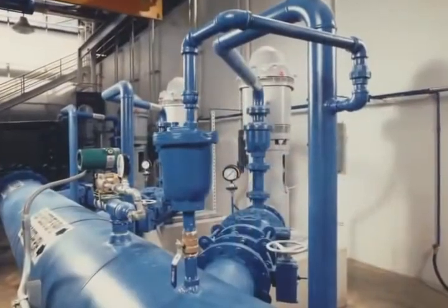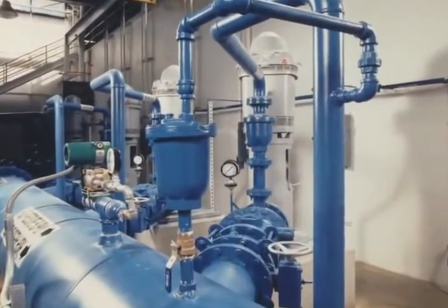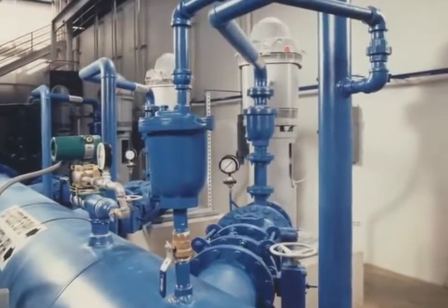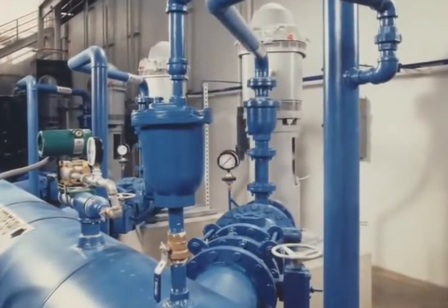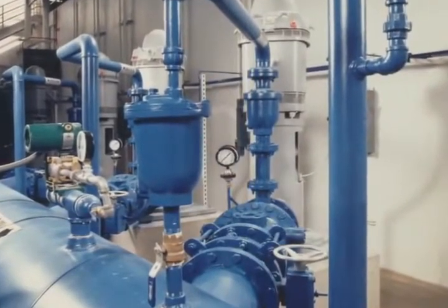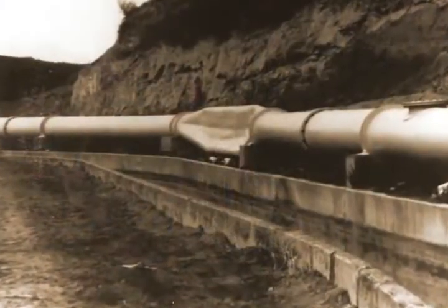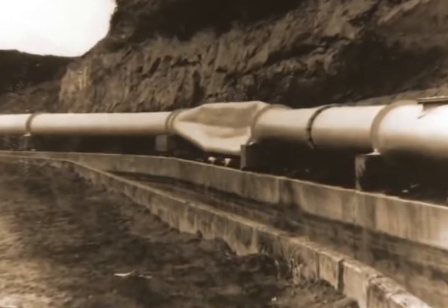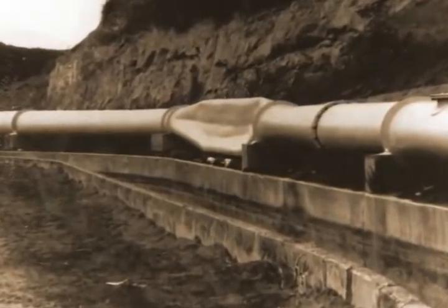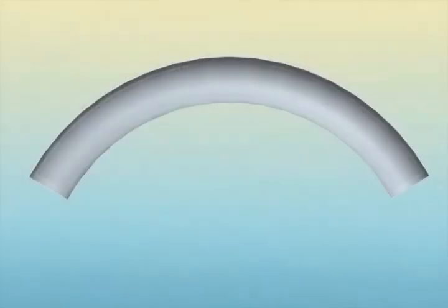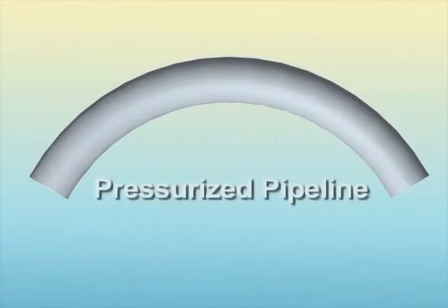In reality, many of these problems are not caused by improper installation of the line, but by failure to de-aerate the line. Properly de-aerating your pipeline will safeguard it from air-related problems. If this isn't accomplished or is done improperly, efficiency will suffer and the pipeline is at risk. Air in a pressurized operating pipeline comes from three primary sources.